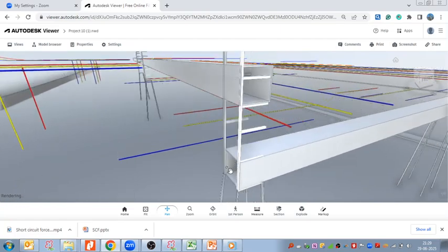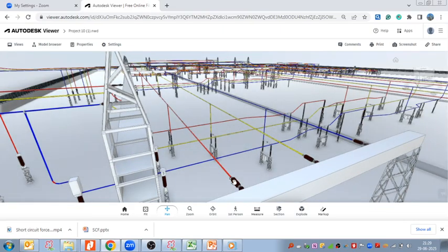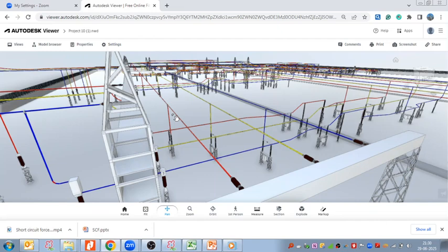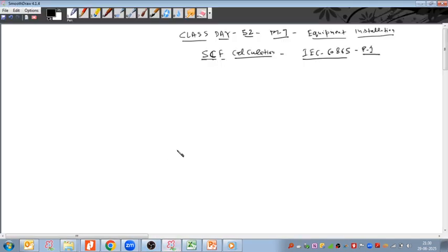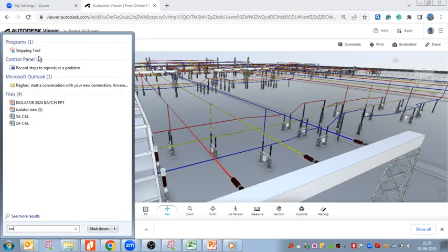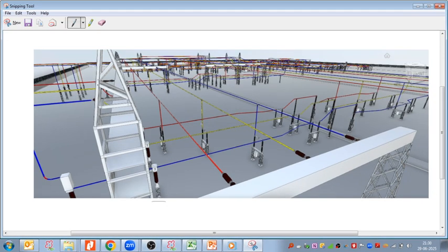Additionally, this conductor stringing we are doing with the help of the tension insulator, right? So if I need to calculate the conductor length, what would be the actual conductor length? Total span minus how much? First of all, minus the string distance on both sides of the tension insulator and structure.